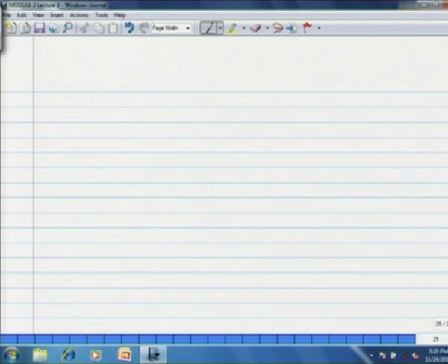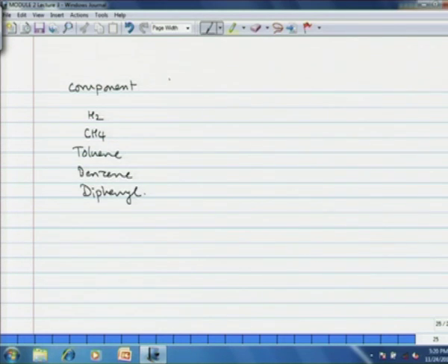What are the components of the HDA process stream that comes out of the reactor? Hydrogen, methane, then unreacted toluene and the two products benzene and diphenyl. The destinations of these components are: hydrogen and methane go to either recycle or purge.